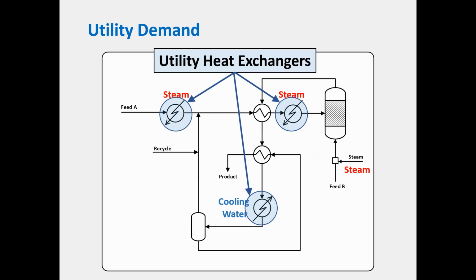These other heat exchangers are what we call utility heat exchangers. So these are heat exchangers which then obviously provide utility to the process stream. They may be heat or cooling, it depends on what's required. Okay, so these two up here where we're supplying steam, we usually refer to these as heaters, and the other ones we can sometimes call coolers. Okay, but they're utility heat exchangers.